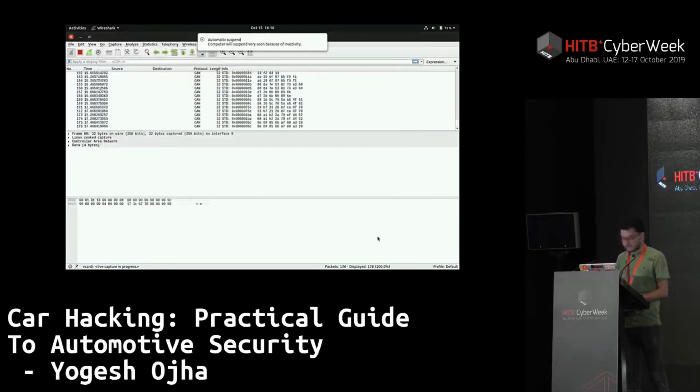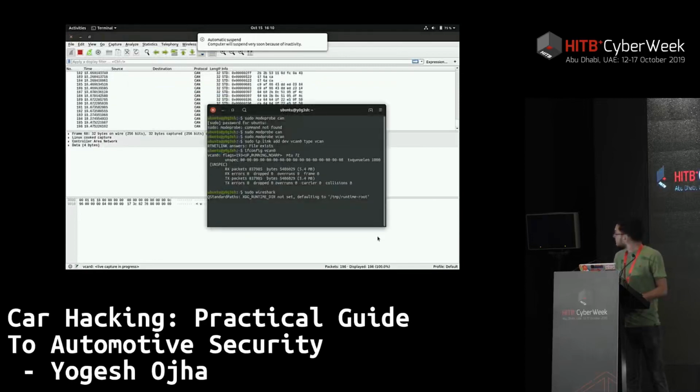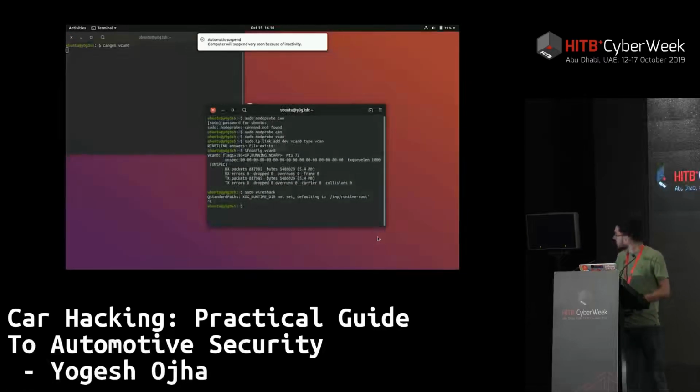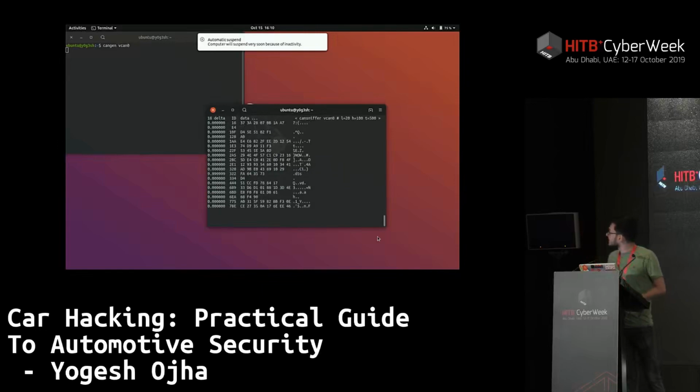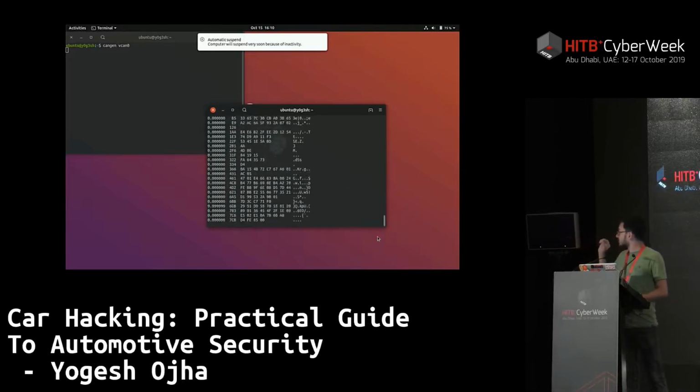You can use whatever tool you feel like, but that can also be done using candump. We'll use candump later. Now we'll use cansniffer on can0. You can see the CAN messages being generated by cangen displayed here, like the same screenshot that I showed you earlier with the arbitration ID and the message.